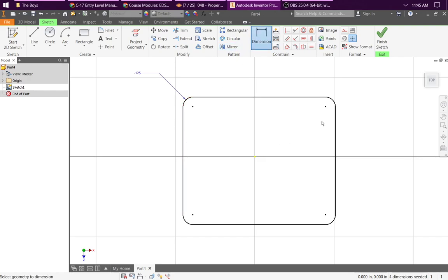And the reason I do the fillet first is just so you can see that when you put in the dimensions, you have to pay attention if you already have fillets, because if you dimension just this line, it's only doing it on the insides of the fillets, and the dimensions that they're giving you in the text are the dimensions of the full distance. So you can click, say, between the lines to get the outside distance.